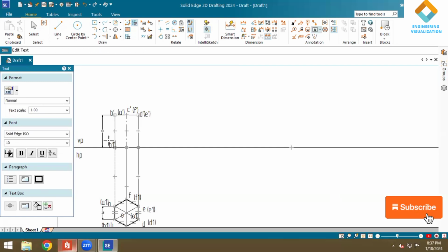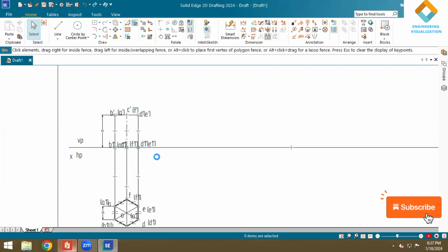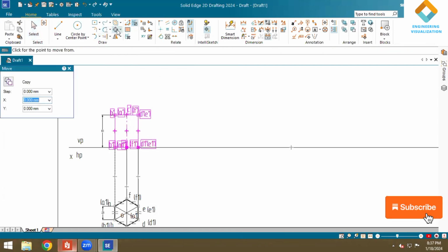So write down the front view notations. Those which are visible are written without brackets, and those which are not visible are written within brackets. Now select the entire thing, use the move command, create a copy and drag it along the XY line.